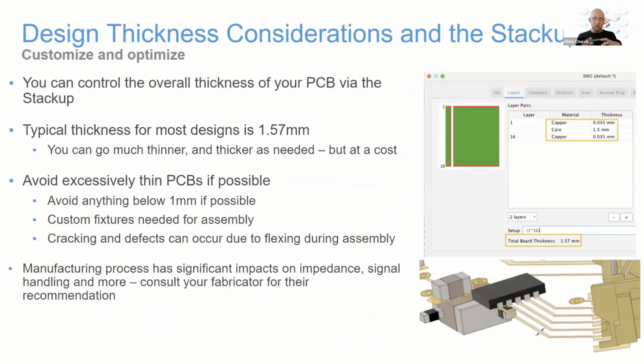So let's talk a little bit more about the stack up itself, and around thickness, because this is something you've either thought about a lot or you haven't thought about it at all until it's really, really critical. So let's just go ahead and get that knowledge laid out so that you're not surprised when it does become an issue for your design. And we see thickness being a primary concern in things like small wearable devices or in devices that have to deal with a lot more vibration, so they want a thicker board, or there's a lot of weight they want to carry in there. So the overall thickness of the PCB is controlled through the stack up,